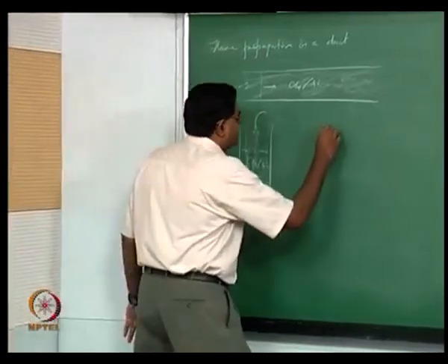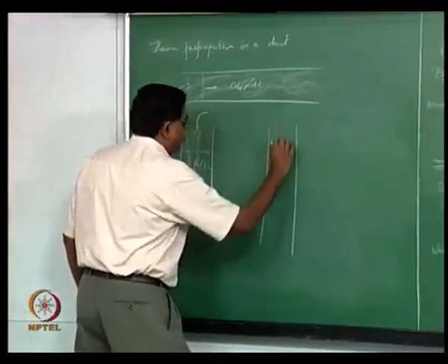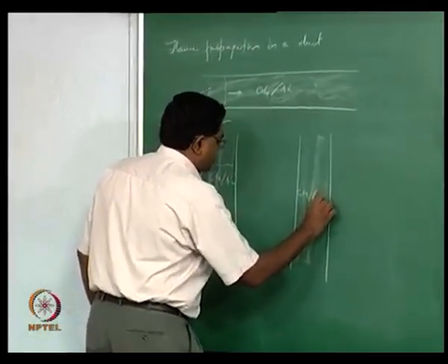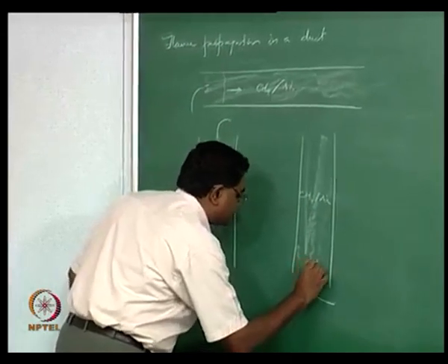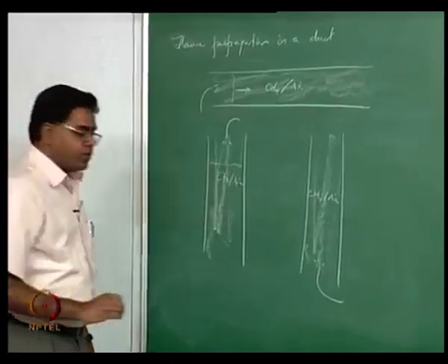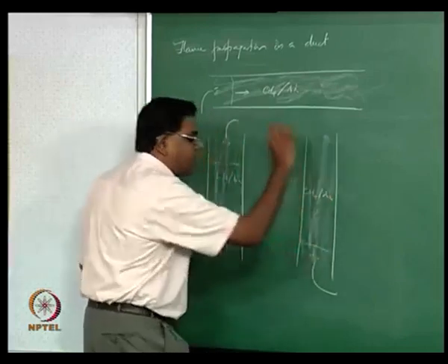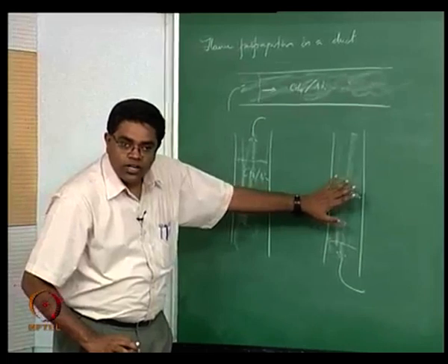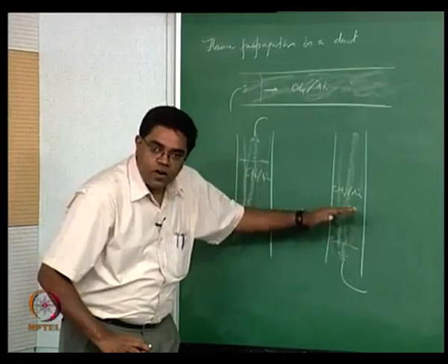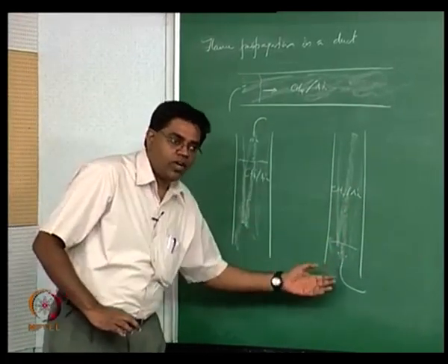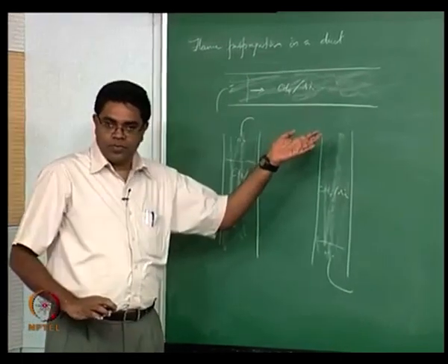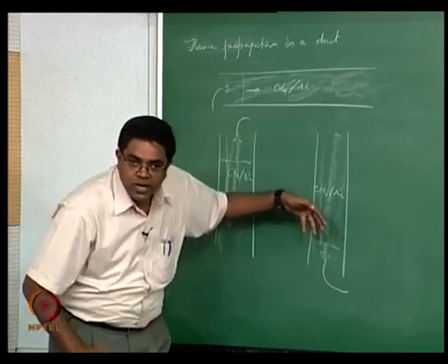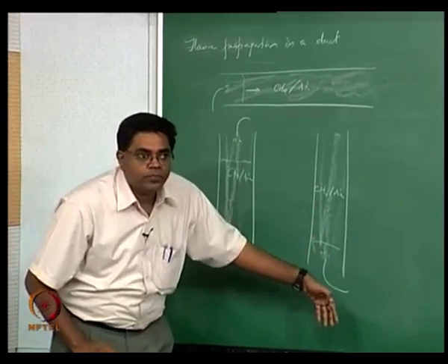But what happens when you now have the same vertical duct and you take the same mixture that is in it but ignite it from the bottom? You now begin to have a flame that is actually beginning to propagate upward. The reactants are cold and they are above, and the products are hot, and buoyancy is actually trying to drive them to go up against the deflagration, expecting the deflagration causing an expansion that is making it flow down, right.